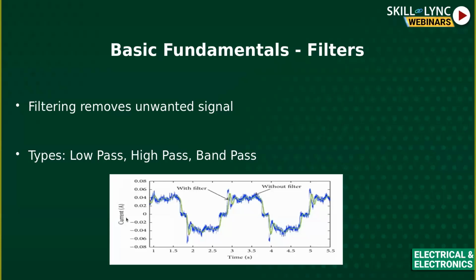There is the low pass filter, which lets the low frequency components pass and blocks any high frequency noise, like these high frequency spikes. Then there could be high pass filters in some other examples where, for example, you want to block any offset or a DC signal, a constant signal, and you only want to let some kind of sinusoidal signal into your system.